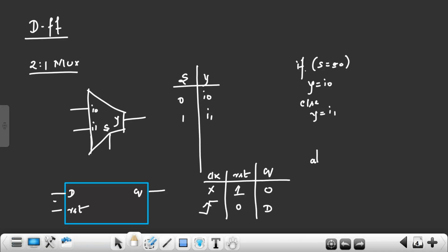Even if I want to use if, then always is required, right? Always @ clock is required. Always @ posedge of clock or posedge of reset, because reset is asynchronous here, right? I should use posedge of reset.